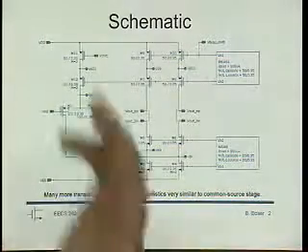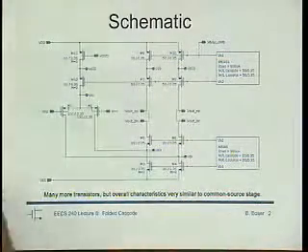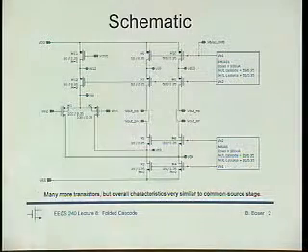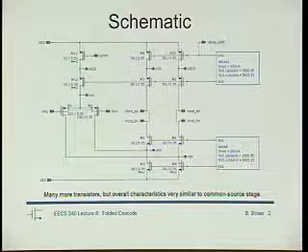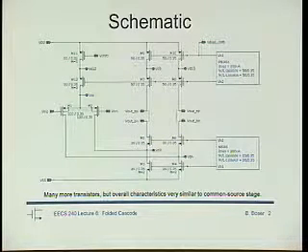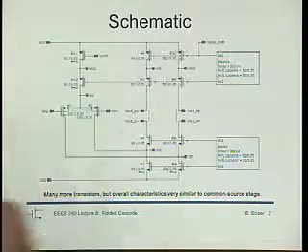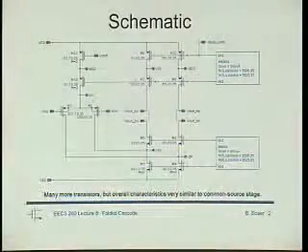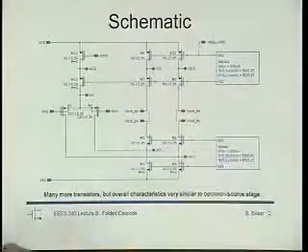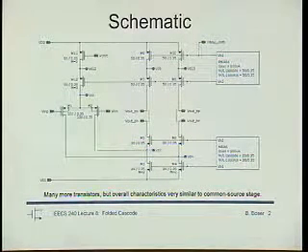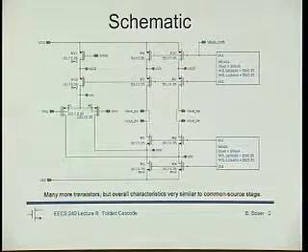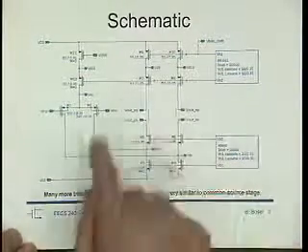Afterwards, you can get, they were a little bit wrong, right? A little bit approximative, what you say from just looking at it. But it gives us a quick idea how the circuit is working. So how is it working? Yeah, but if you can use the microphone, please. Probably a dominant pole at the output node, the high impedance node. Maybe a second pole at the input. There is a dominant pole there, yes.